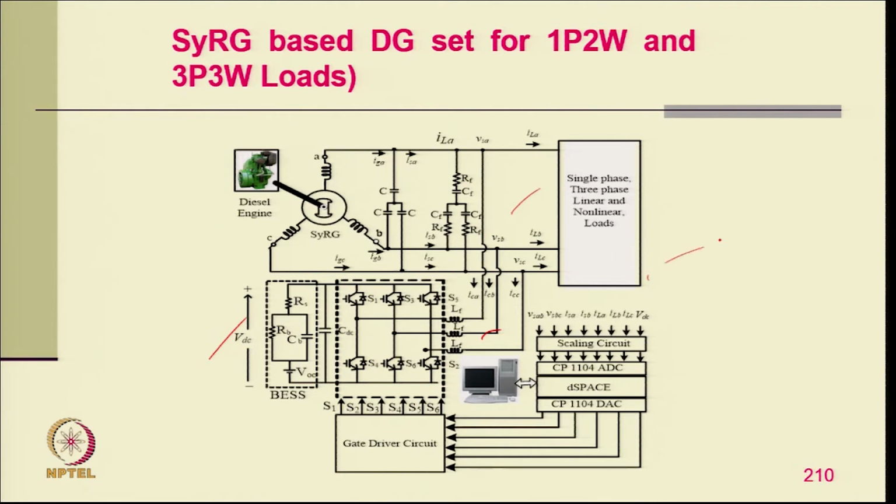even during dynamic load, and we can operate this DG set at what we call optimum fuel utilization, so that the generator is not loaded less than 80%, not more than 100%. If the consumer load is more than 100%, the battery provides the power through the converter, and if the load is less than 50%, the battery charges. Even during dynamic load, this converter and battery are capable of giving extra power beyond 100% of the generator, but we are not taking more than 100% power from the generator. So, generator voltage, current and power are not affected by the dynamics of the load; the converter takes it, because it provides fast dynamics.